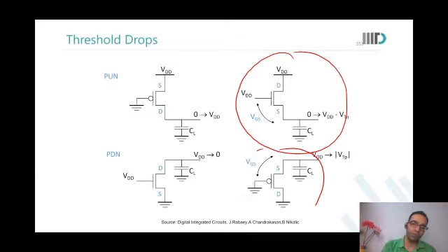Dekho na? Yes. Okay. When the NMOS is in the pull-down network, your output will go to 0. Otherwise, your output will only go to VTP. It will not be able to go down to full 0. But then why are they calling it VT drop or threshold drop? Because that is what happened now. 0 was expected to be transferred here, but 0 could not be transferred. It got limited by the VT of this PMOS. Okay. Is that okay?